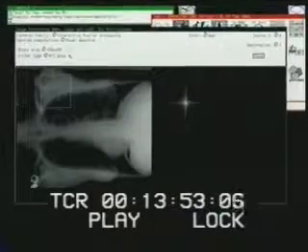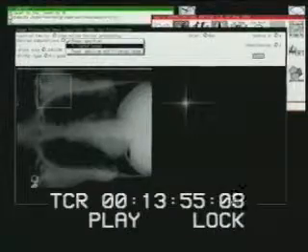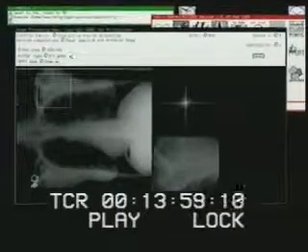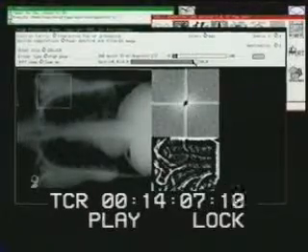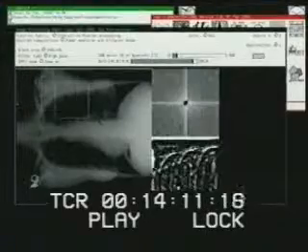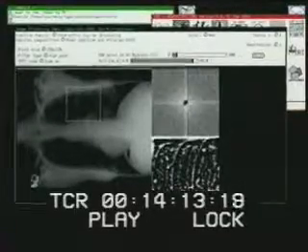We can also, if we like, not just display the power spectrum, but do a filter and then an inverse FFT. Let's do a high-pass filter. We have to reduce the frequency of the filter and increase the gain. And so now when we move this box around, we're doing 128 squared FFT, high-pass filter, and inverse FFT on the fly.